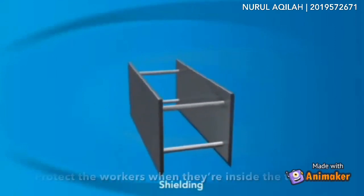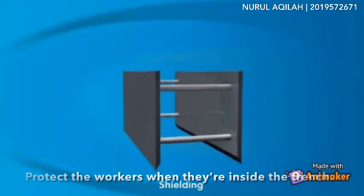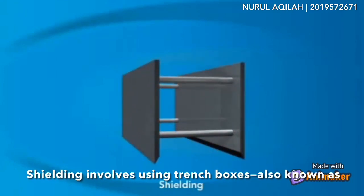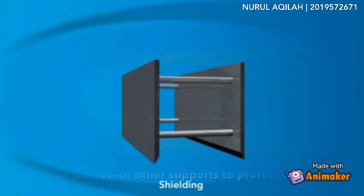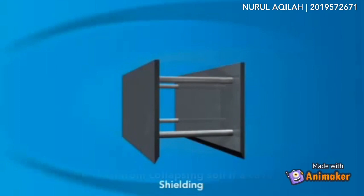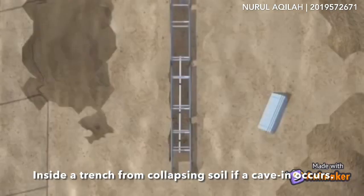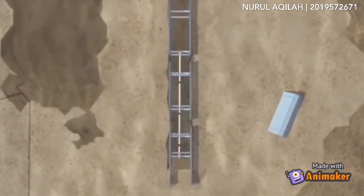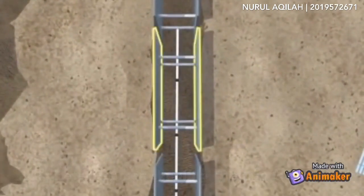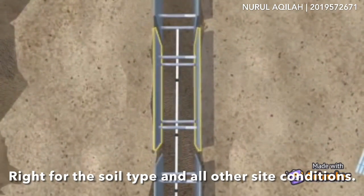Shielding is to protect the workers when they're inside the trench. Shielding involves using trench boxes, also known as trench shields, or other supports to protect workers inside a trench from collapsing soil if a cave-in occurs. The competent person should pick a trench box that is right for the soil type and other site conditions.